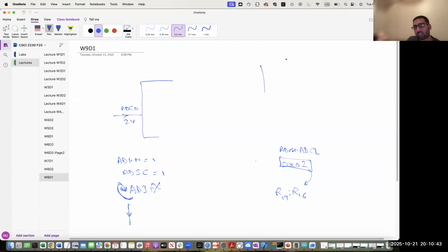and in that specific location you can put a code, which is known as the interrupt service routine, right? Which is basically doing the same thing that you were doing here manually. So you can put your code here. You can say, okay, R17 down R16, put in them the value from ADCH